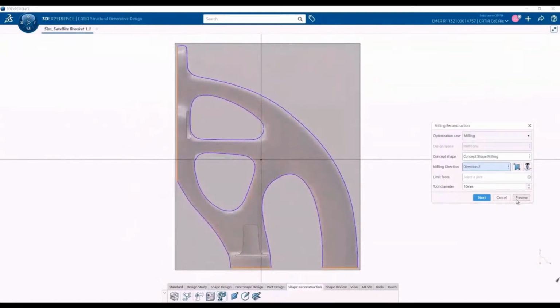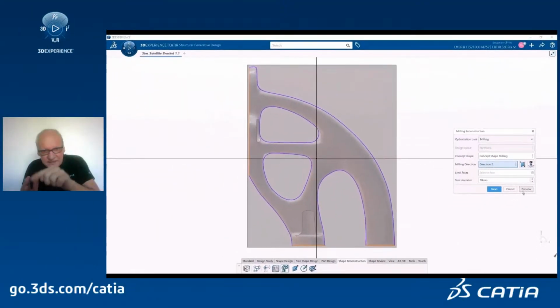So far, this silhouette is only a set of polylines, okay? So now the user will have to assimilate all those shapes to maybe a circle, maybe an oblong, maybe a polygon with fillet, maybe keep this as it is, a spline. And you will see that it's where we introduce AI in CATIA.